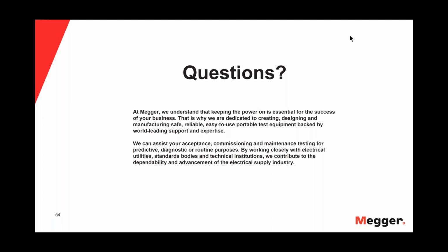and maybe half lap. So when it's brand new, the lap-to-lap contact is excellent because there's no corrosion, nothing. You have basically like a copper tube, so you get an excellent TDR picture. It's no problem, excellent TDR trace.